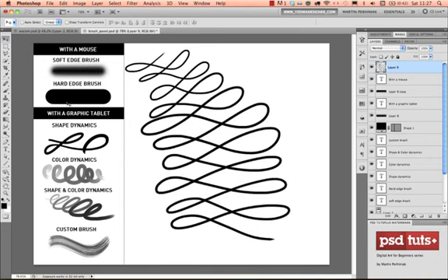And if I select the brush, which can be selected from the toolbar, or you can also press B as brush on the keyboard. So now I'm back to my brush tool, and if I press 0, that will set it back to 100%. If I want to have a specific opacity like 25%, I press 2 and 5 after one another. So 2 and 5, and now it's set to 25%. And you can see the change on the opacity of the brush.